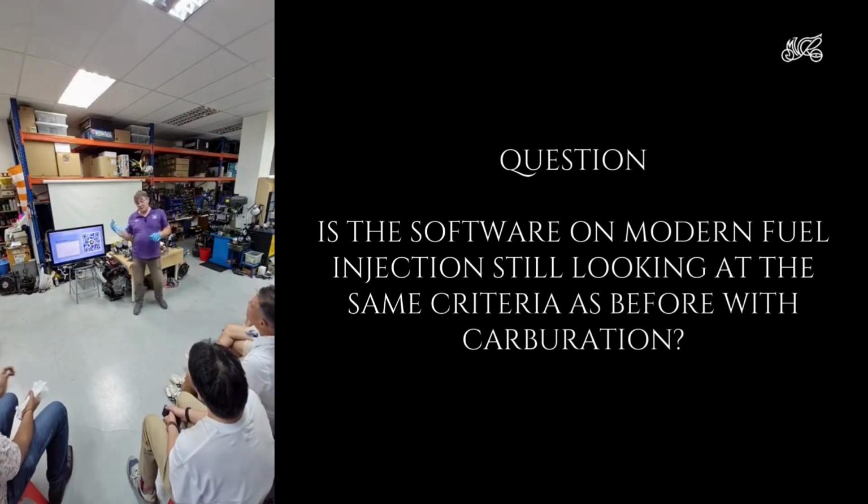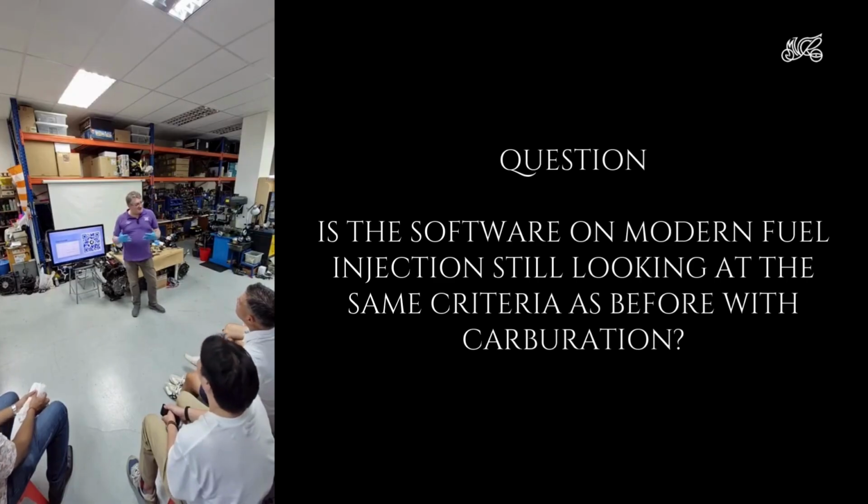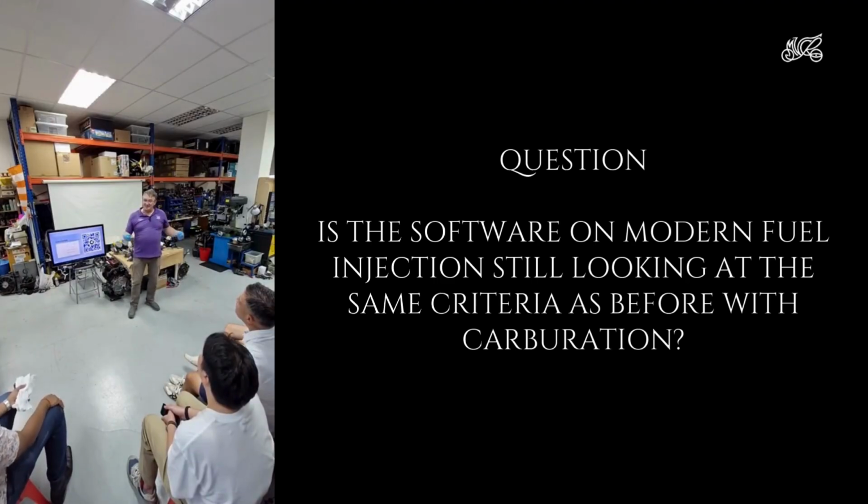And of course, the other thing which these late ECUs have got is onboard diagnostics, at the requirement of the US government. So go back to that L-Jetronic system, my car with the two computers. When that car goes wrong, you're really on your own, right? Because there's no information about what's happened, and you've just got to start changing things to work out what the hell happened.